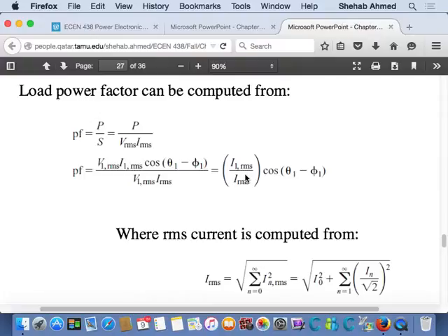It's not possible because anytime you have a cable with current, you have an inductance. So you definitely have a reactive, inductive system. But there are some loads that can be leading power factor, like capacitors, or synchronous machines running in leading power factor mode. But if the overall power factor of the system is leading, the generators at the power system, at the utility, will be affected. Again, that's a 459 topic, but just take it from there. So you always need to be lagging in power factor or unity at best.